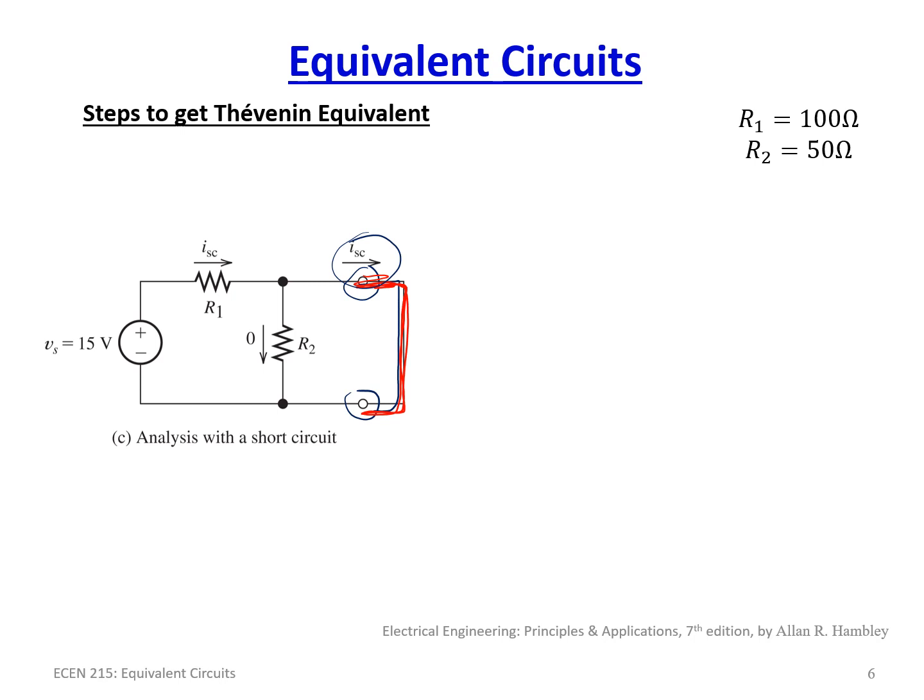So for the first step, we're going to look at what is going on here. Since we've got a short here, the voltage drop across R2, right here, is equal to 0 volts. Why? Because it's got a short across it. This is equivalent to us putting in a 0 ohm resistor here. So just real quick, because there are going to be some test questions actually dealing with this: a short is simply a 0 ohm resistor when it comes to analysis. So you could replace this wire